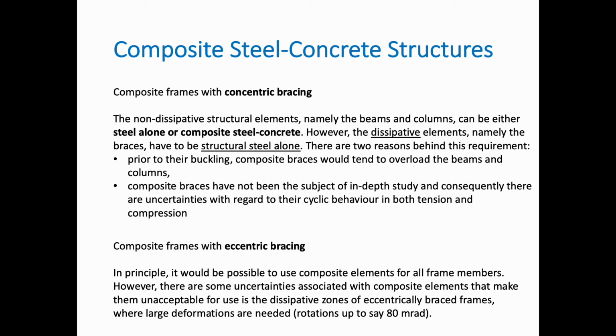Lastly, looking at composite frames with concentric bracing, the non-dissipative structural elements can be beams and columns of steel only or composite. However, the dissipative elements, the ones that we want to buckle and provide the ductility to the system, they have to be steel only.